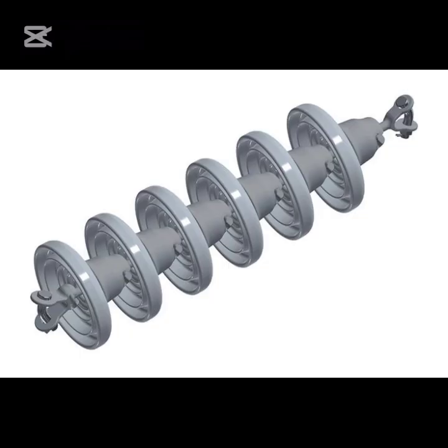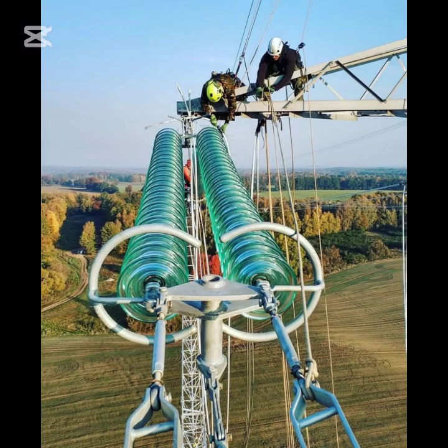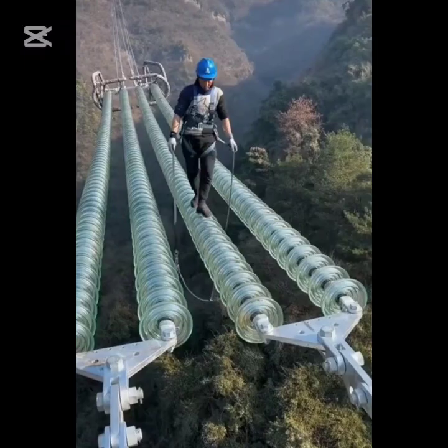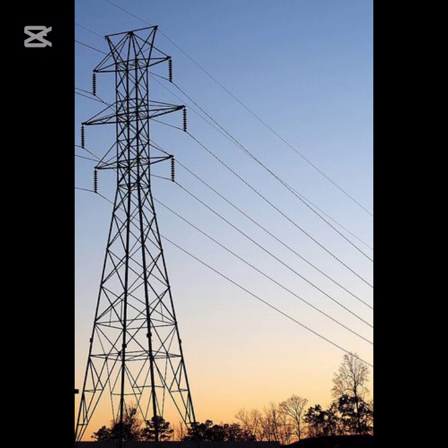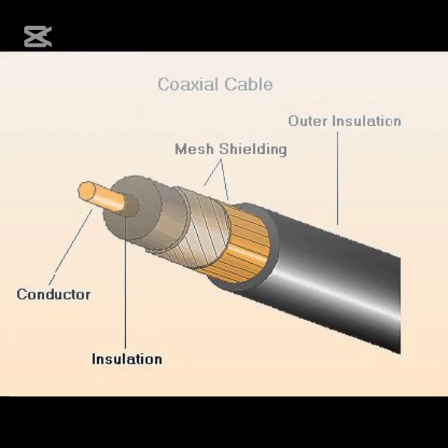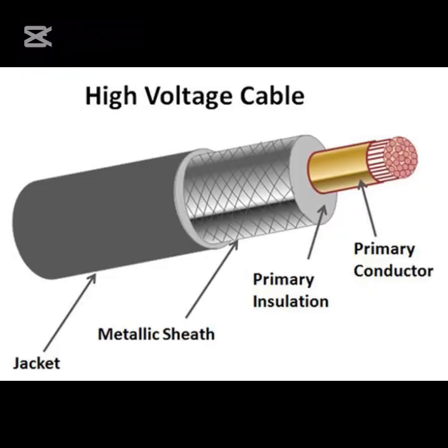1. Insulation materials. Use high-quality insulation materials with low dielectric losses and high resistivity. 2. Insulation thickness. Increase the insulation thickness to reduce the electric field strength and minimize leakage currents. 3. Conductor spacing. Increase the spacing between conductors to reduce the electric field strength and minimize capacitance. 4. Shielding. Use shielding materials, such as copper or aluminum, to enclose the transmission line and reduce electromagnetic interference.